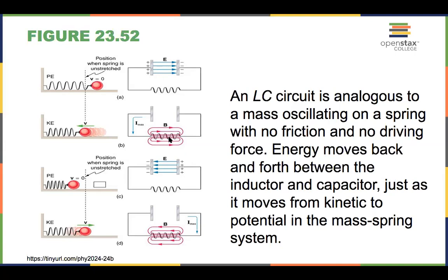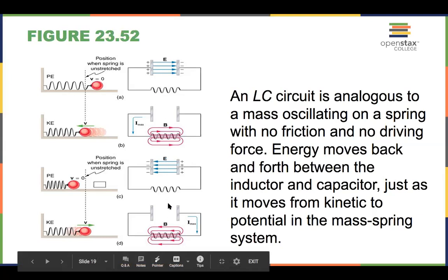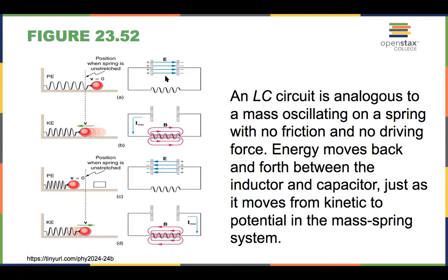Now the inductor is fully charged, with the energy fully stored in the magnetic field. After that, the energy is released again, so it becomes charge on the capacitor again. This process goes back and forth all the time. Energy is transferred from electric field to magnetic field, and then the other way around, from magnetic field back to electric field. This is a resonance, coming back and forth.